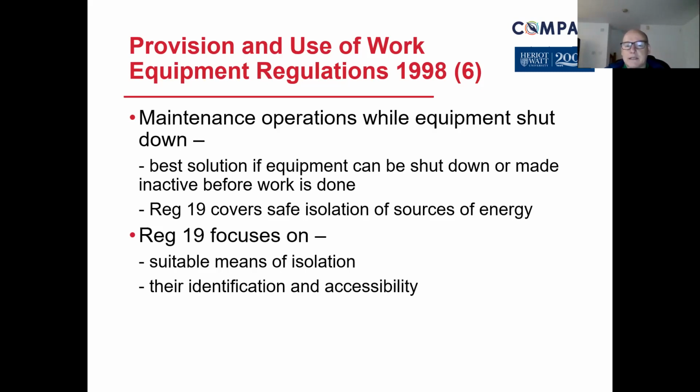So there's this aspect of what you do and what you don't do inside the danger zone, and therefore people need to know this and it needs to be identified as well. There's also the issue of overriding and bypassing safety switches, interlocks, and the situation that could lead as a result. If he'd have isolated the whole machine and de-energized it, then that plate couldn't have moved down. It would have stayed in a safe state.